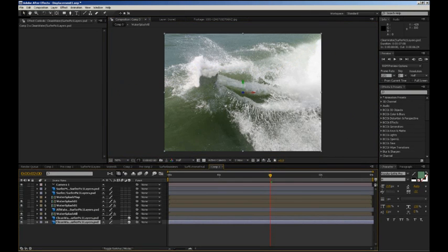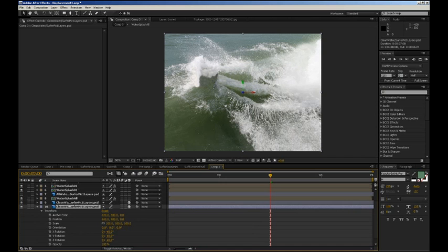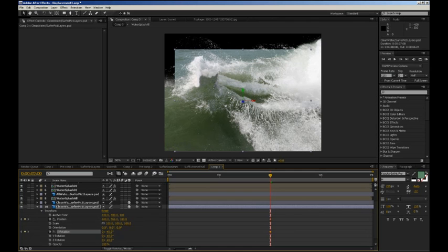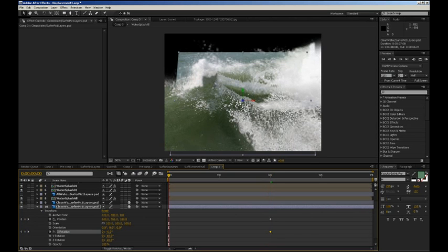And then with the layer that I have in the back, I'm going to position that at 108 on the Z-axis. I'm going to bring it a little higher as well, 556, actually lower on the Y, and then rotate on the X-axis -6 degrees. And since I set these keyframes here, let me set them at the beginning as well, because this is where I want this to be at the very beginning.